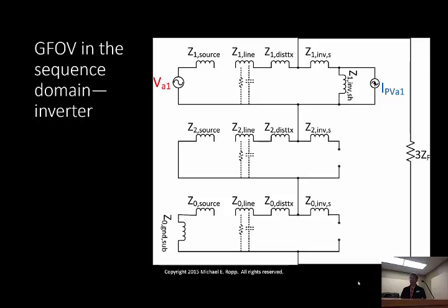Where does that continuity come from? Well, this is why it becomes critical that if you're going to talk about the sequence networks, when there's a current source in there, I have to put in the loads. That's the continuity. That's where the path is. That always scares us a little bit as power engineers, but that's where the PV current was going in the first place, right? This isn't an overcurrent. It is the current. It's the PV output current.